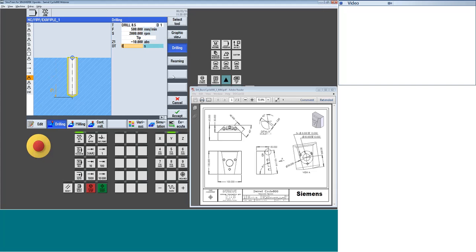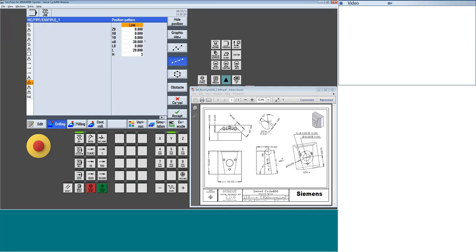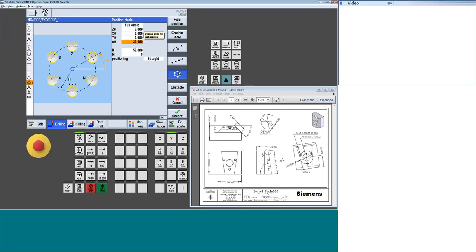And I do just like I normally drill. I'm going to link it to a bolt hole pattern. Top 0, 0, 0 center. All right. So I know my included angle on this. I got 120 degrees. The radius I happen to know is, well, I know the diameter, so I'll calculate it. I have 3 holes, and actually no, I want to start at 270. Sorry, I'll start at 270. Okay.